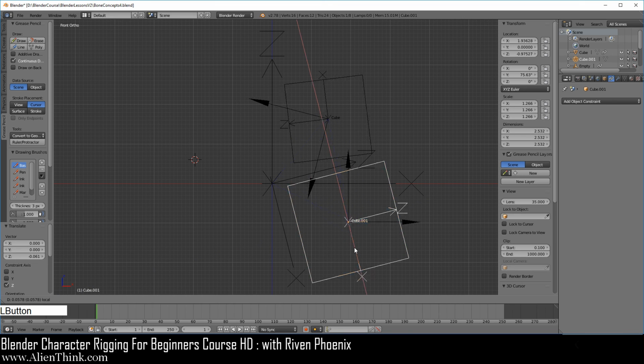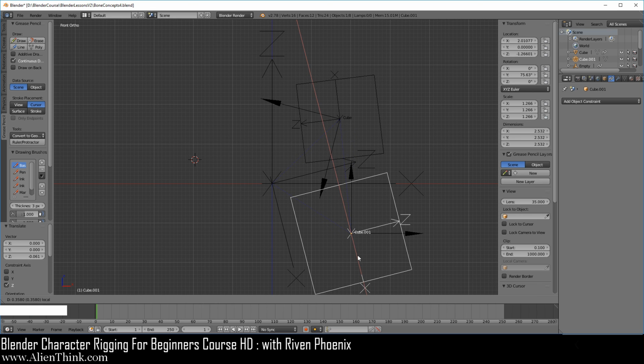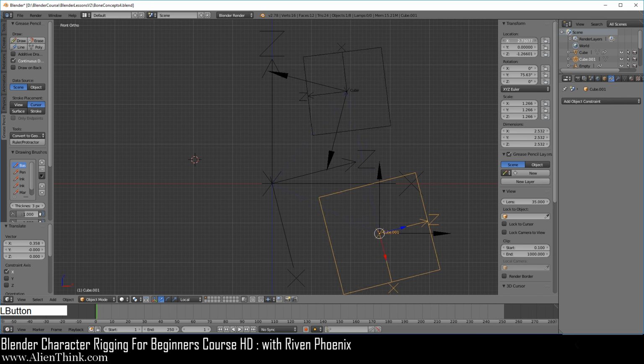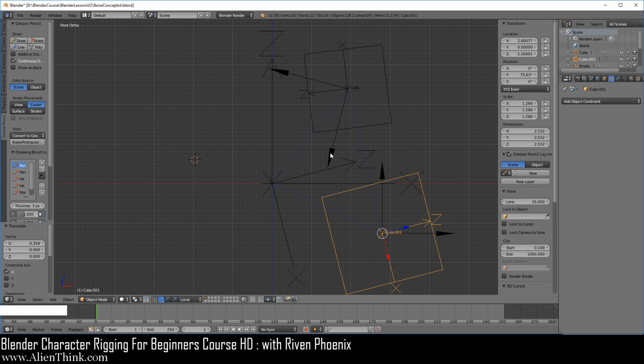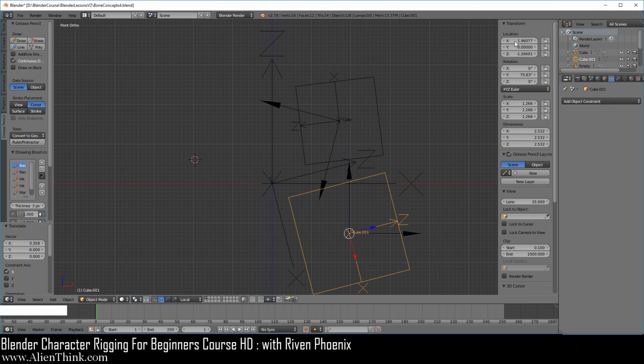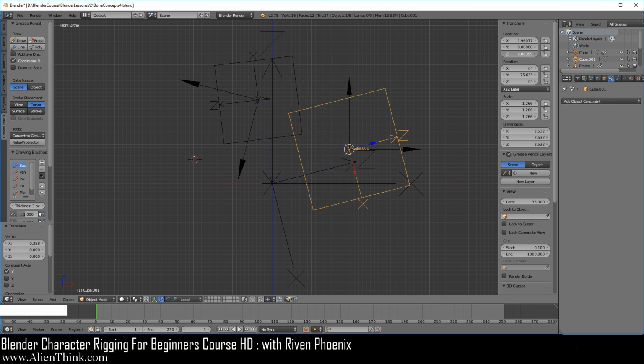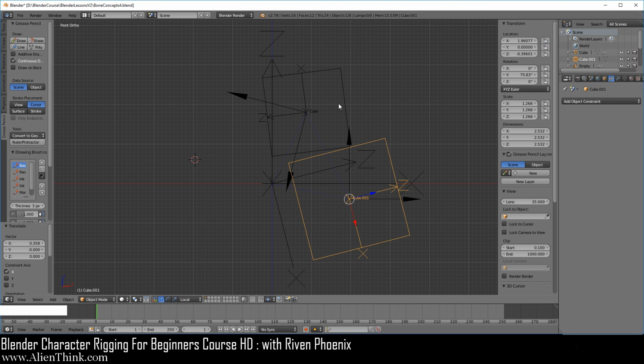Now when we click on x over here, this is going to move along the global x. Now when we click over here on the x, which is really now acting like its local axis, you'll notice that this is where the arrow is pointing. And now when we click on z, you'll notice that that's where the arrow is pointing for the z.